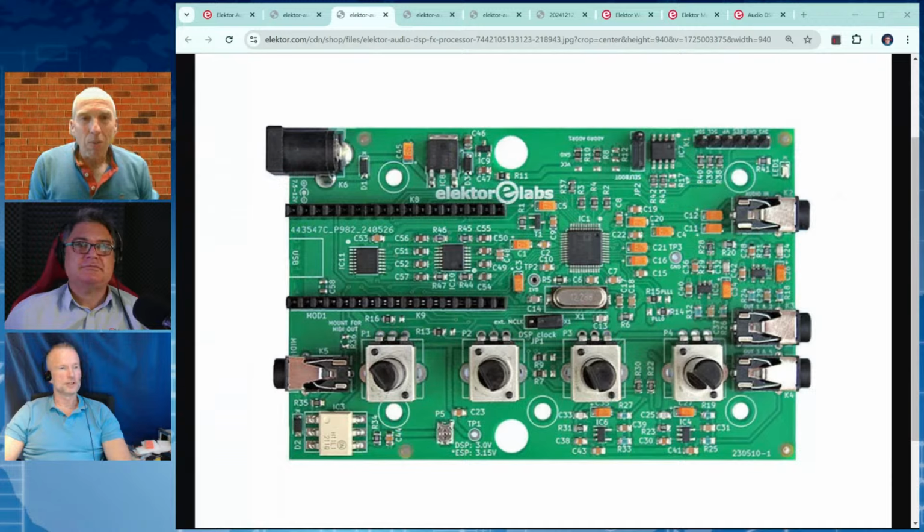So that's why the connector is mounted with that polarity. Is it safe if you mix up the polarity? Yes, there is a diode. You can see it right behind the connector. It's called D1, in the top left corner of this photo. There is the polarity protection.